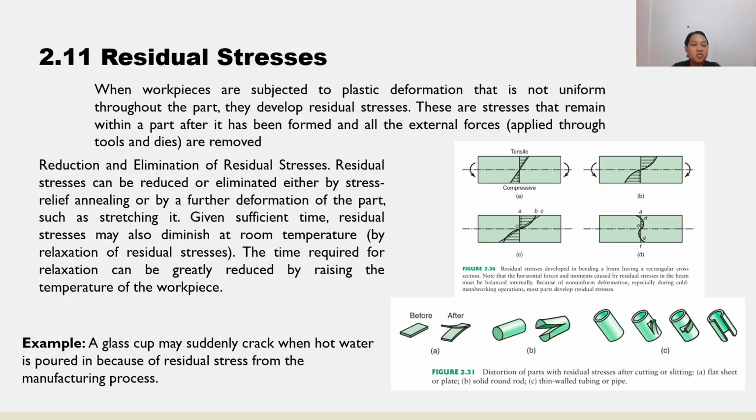Next, we have residual stress. When workpieces are subjected to plastic deformation that is not uniform throughout the part, they develop residual stress. These are stresses that remain within a part after it has been formed and all the external forces are removed. Reduction and elimination of residual stress.